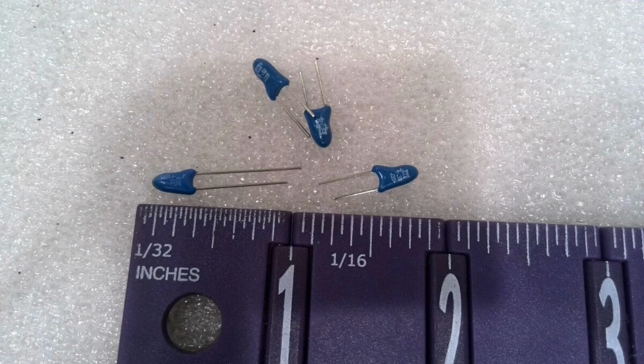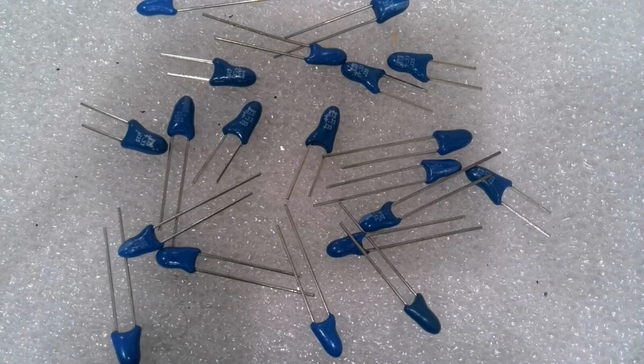Summary of construction layers. Tantalum anode, the core structure, providing a high surface area for charge storage. Dielectric, tantalum pentoxide, a thin, high-quality layer for storing charge. Cathode, manganese dioxide or polymer, a conductive layer that allows the capacitor to discharge stored energy. Carbon and silver layers, intermediate layers that improve conductivity and connect to external terminals. Encapsulation, protective covering that shields the internal components from damage and environmental stress.